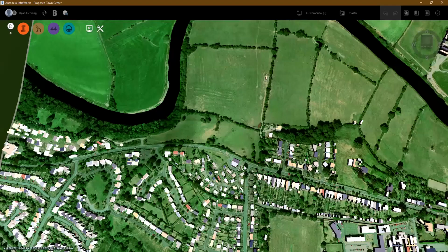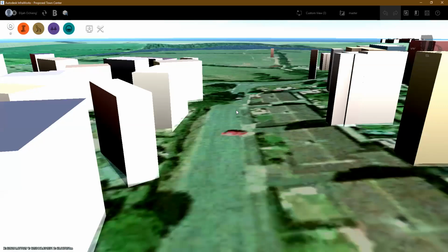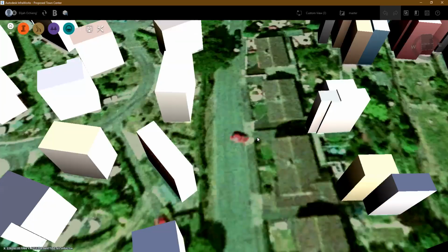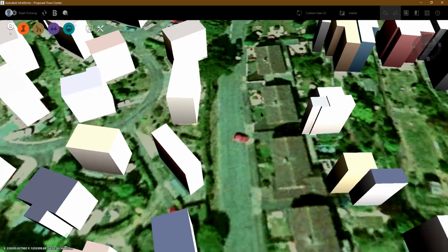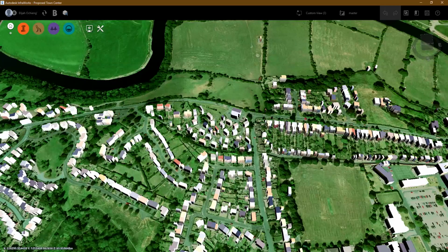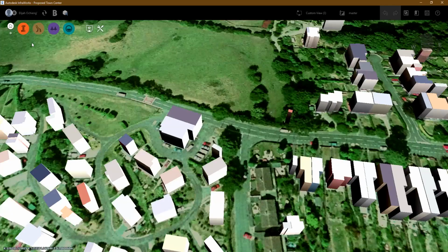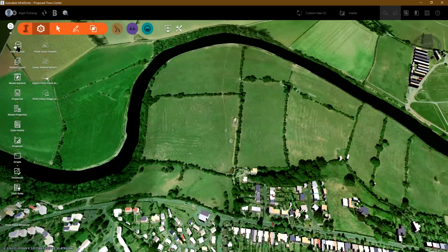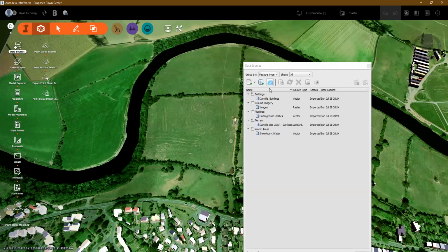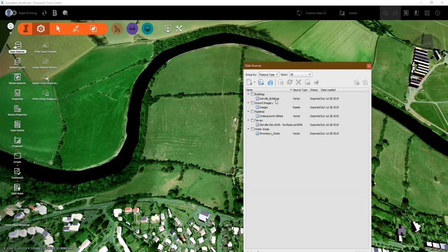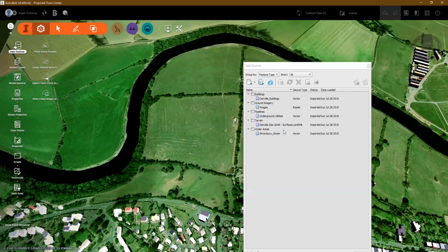So you can see here, we have got very good detailed GIS information in terms of the imagery, the terrain model, and also the shape models for the buildings, how they exist on that particular project area within InfraWorks. So basically you need to bring that in. If you know also of late, right now it is possible to link up InfraWorks with ArcGIS. So if I wanted to link it with ArcGIS to bring in those different detailed information, I'll go to the GIS connector, which will open up ArcGIS Online that can now allow me to start working and bringing in the GIS information just to build the context of my model.